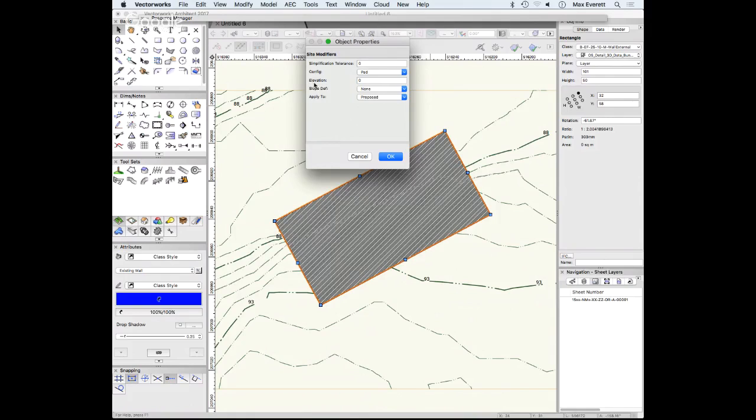The site modifier has an elevation, which is the important bit, the next step, because you're looking at your site and you see the contours. It's at 93 meters above sea level, and we're cutting through 88 as well. So we could choose a figure slightly higher than 93, so let's say 93.2, and pop that in.